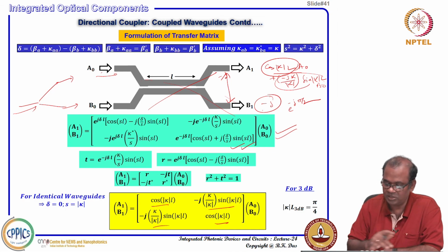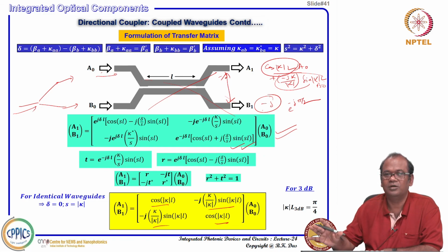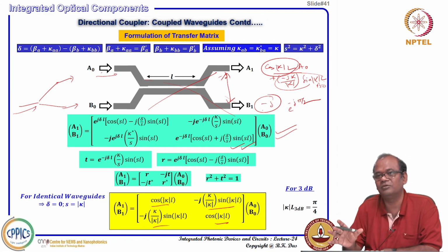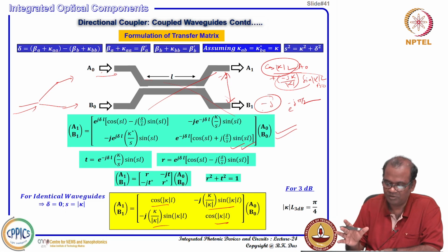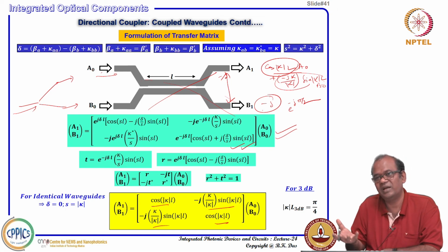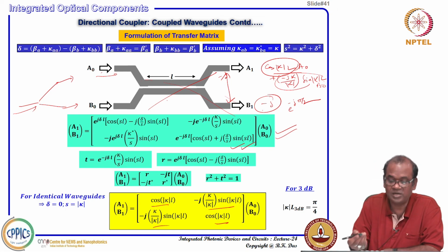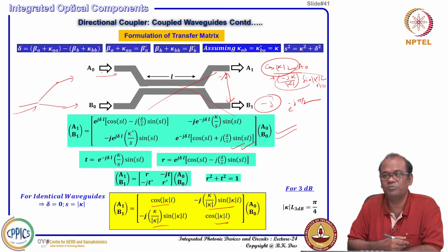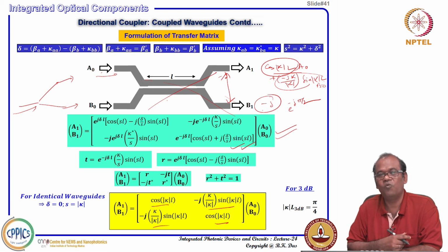Okay. From here onward we will be discussing forward. For many other devices, complicated structures, complex circuits, this directional coupler is actually the basic building block, and we can take help of this structure to understand other components like the Mach Zehnder interferometer. As I said, this directional coupler is more fabrication friendly for the silicon on insulator platform than the Y junction.